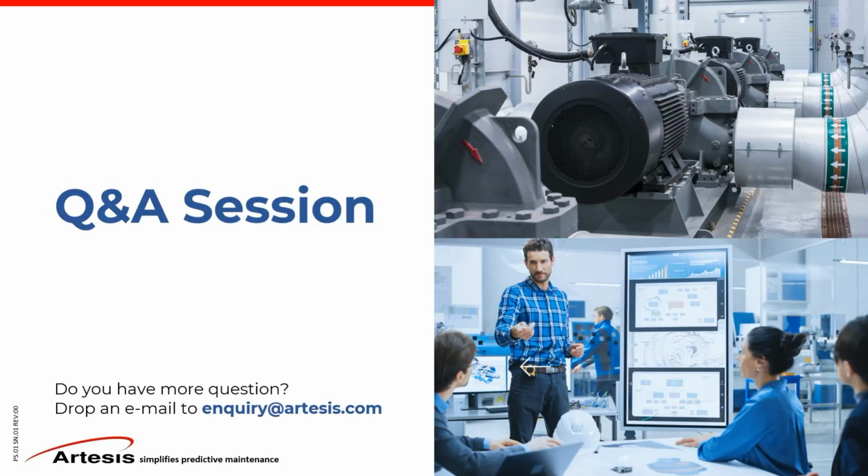You need 3 CTs, current transformers, which will sit there again permanently, and you will make a network connection to either an on-prem switch or, if you want to go to cloud, you can do that, and then it can be remotely commissioned, and that's it, you're good to go. And in order to commission the unit, all you need is the motor nameplate information: voltage, current, frequency, RPM, and then that's it. So it's an easy setup.